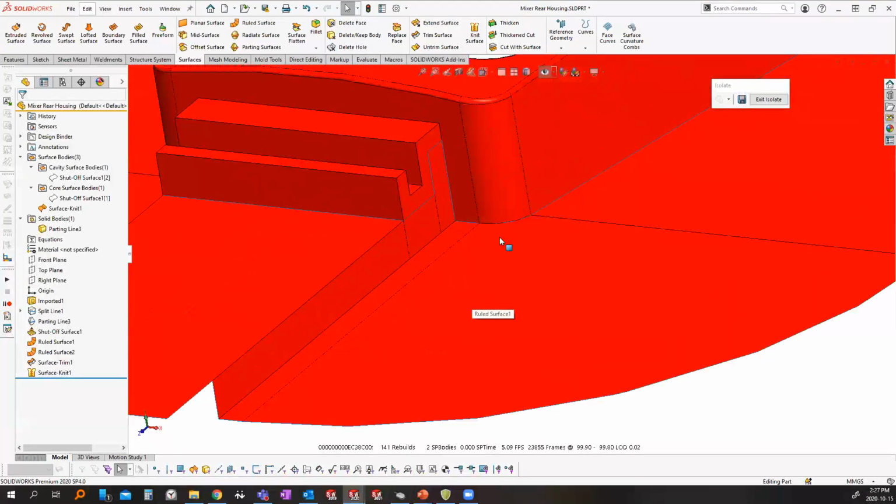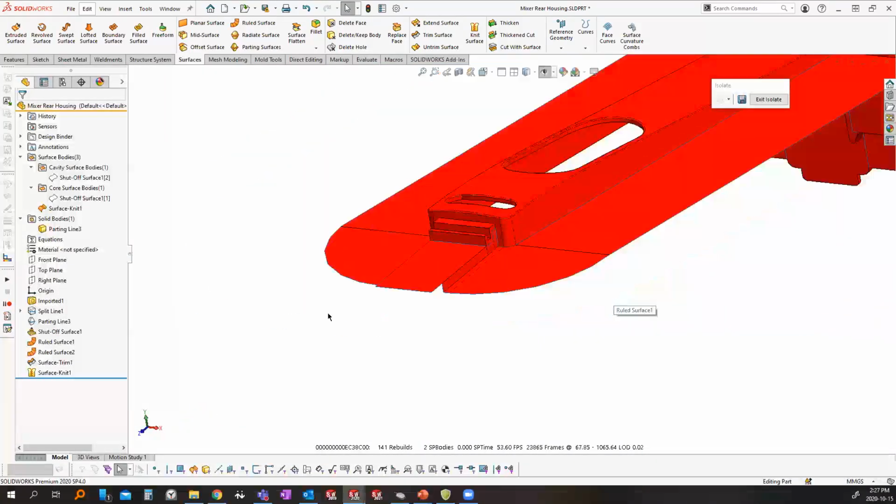A good indicator to just visually tell where you have open surfaces is this kind of blue outline. If I have joined edges, you'll see a black outline. I have my settings set to, if there is a tangency, to show a phantom or dashed line. But if I have surface bodies specifically and open surface bodies, I'll see this blue edge. So I saw right off the bat that all these blue edges along here went away. So I don't necessarily need to look at my solid body folder.